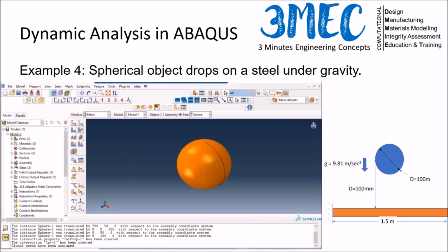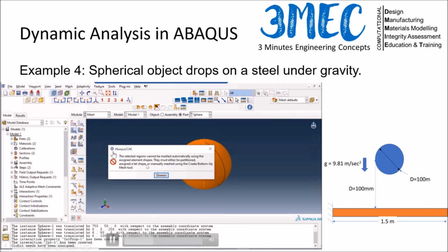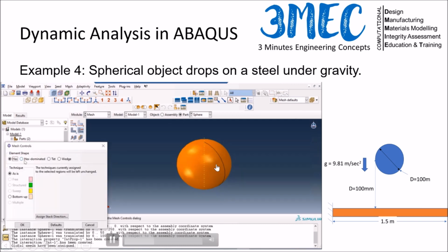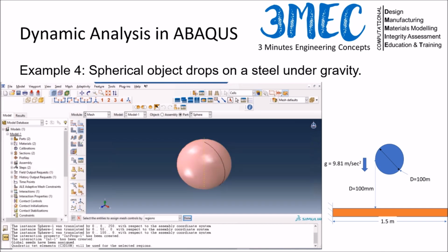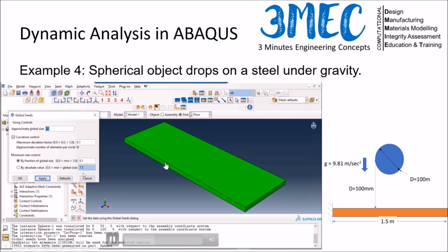And now I'm trying to mesh each component. Again, the same issue. Either I should divide it into small parts or use a very fine mesh. So what I'm going to do now is I'm going to use a tet mesh at the end of the day. So I'm going to go with a tet mesh now, and it should be easier than meshing complicated objects. But it's recommended when you have a tet mesh, try to use quadratic elements to avoid any volumetric locking and other issues, which again I have spoken about during my lectures, Introduction to FEM.